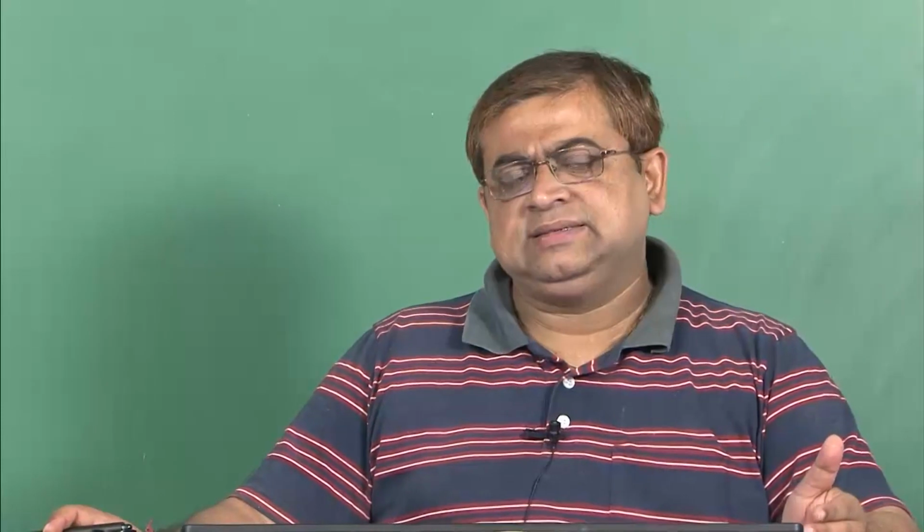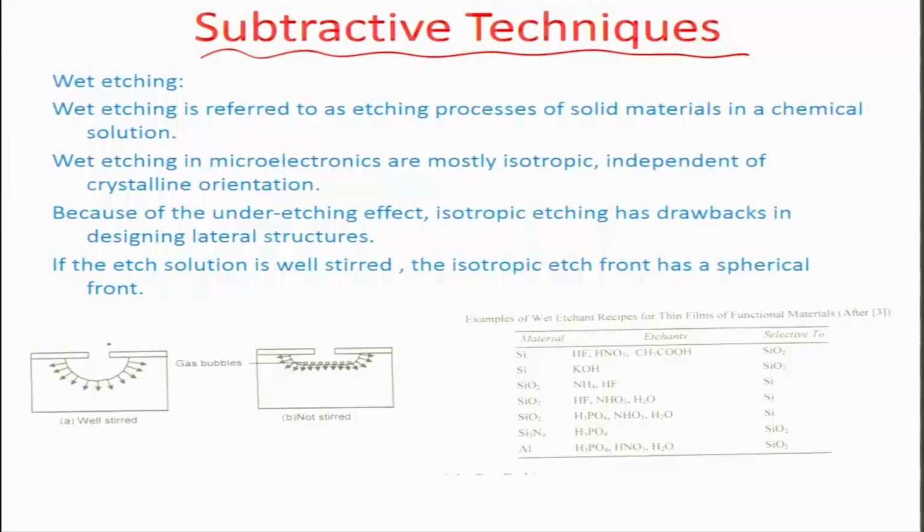Typically you can categorize the wet etching techniques into either isotropic form or anisotropic form. In the isotropic section, we mostly discuss homogeneous material etch processes. Etch rates are similar and not a function of the direction in which etching is taking place. On the other hand, the anisotropic chemistry depends on the direction. And so, typically what we do in microelectronics is shield an area and then create a small window or a via through which you can then take the etchant.